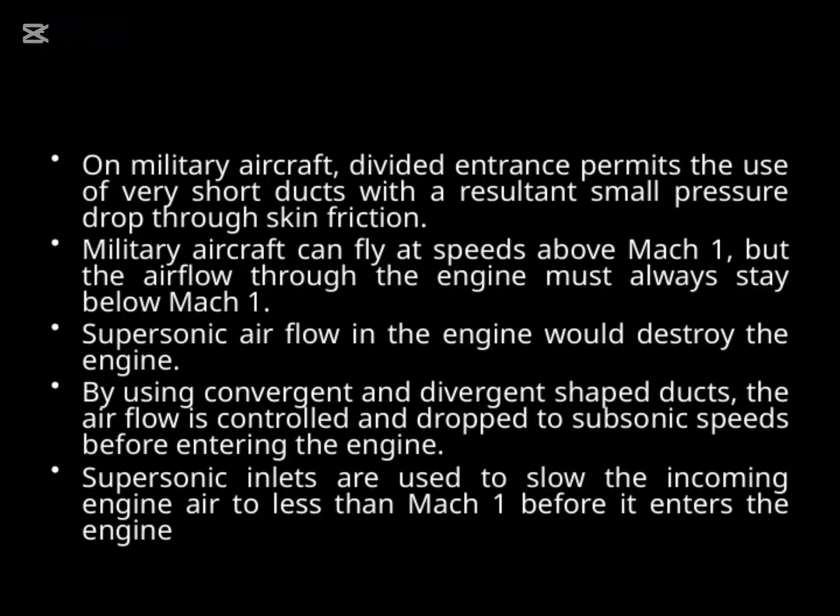To prevent this, engineers use specially shaped ducts, either convergent or divergent, to control and slow down the airflow before it reaches the engine. This is what we call a supersonic inlet. Its purpose is to slow the incoming air to subsonic speeds, ensuring the engine operates safely and efficiently. So, in essence, these inlet designs are critical for maintaining the right airflow conditions, especially when dealing with high-speed flight, and they tie directly into our broader theme of managing airflow for optimal engine performance.